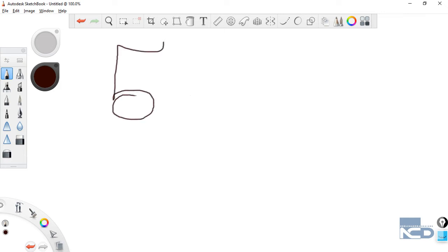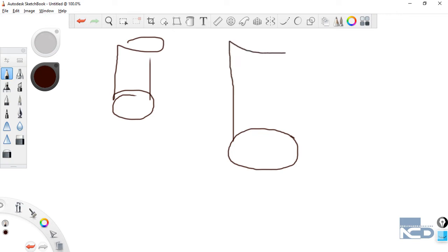For creating a cylinder we just have to create a circle first, and this circle is known as a feature, which is a 2D shape that we create with the help of the sketching module, and later on with the help of some tools we give it a certain height, and with that height it is created like a cylinder.